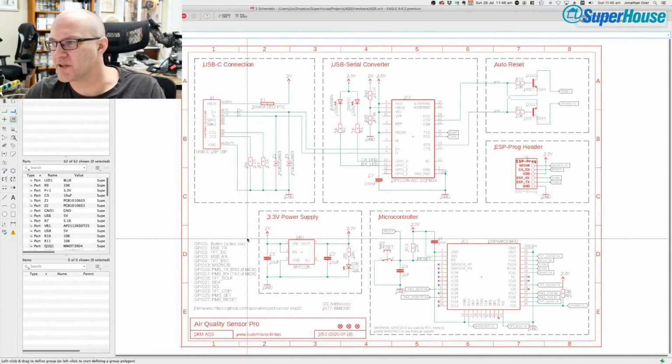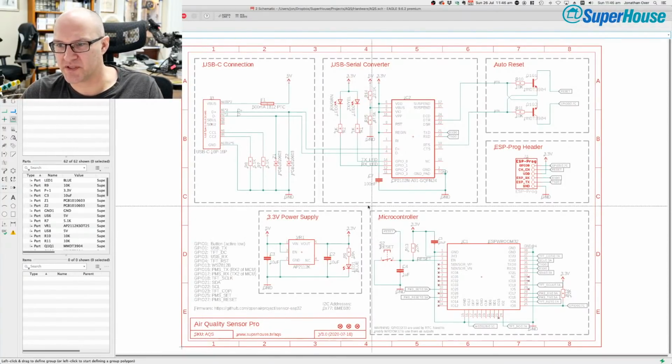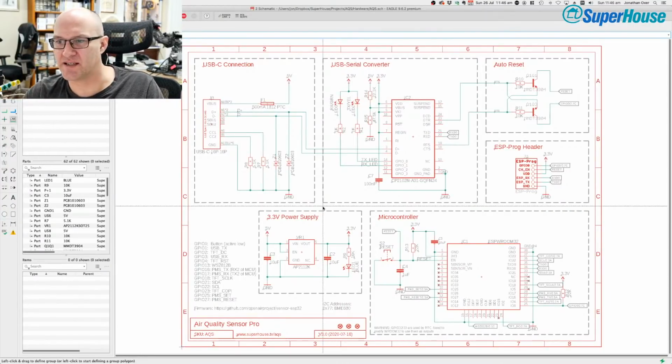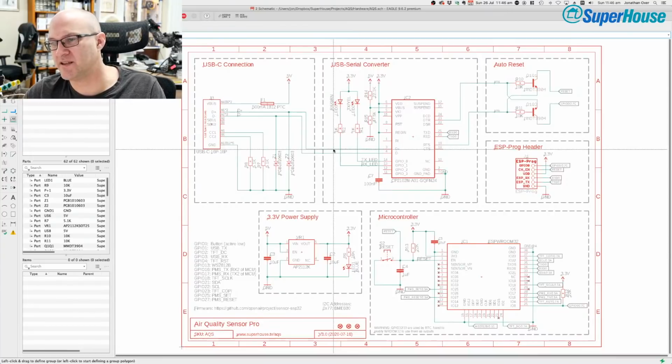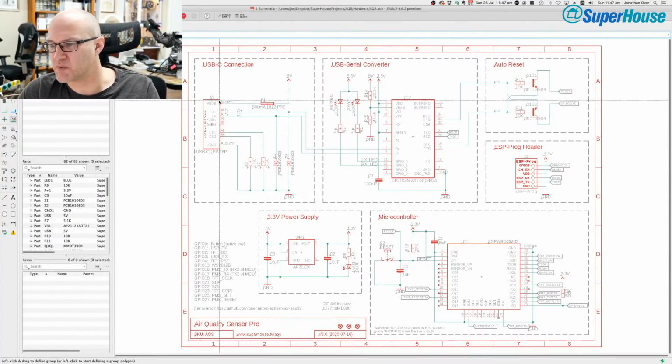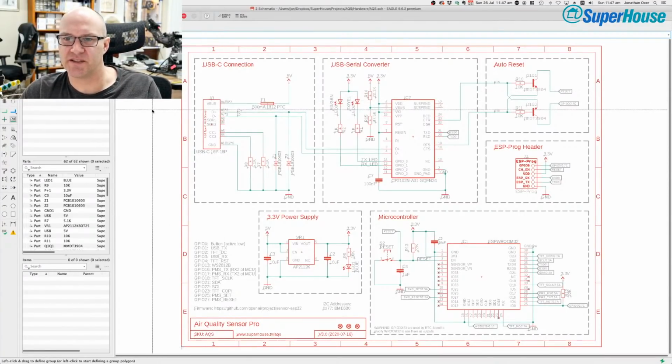So normally what I would have is these 3 views open on the 3 screens all at the same time. They're all in physical view, and you can click on something in one view and it highlights elsewhere. So you click on a net in here and it highlights the track on the PCB, etc. Which I know you can do in KiCad now as well. But it really used to bug me, the disconnect between the schematic and the PCB in KiCad.